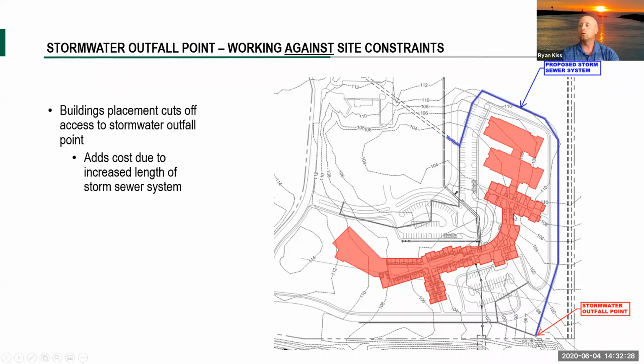it's kind of a longer, irregular shaped building, and it's doing a couple things to us. One, with the topography, that natural drainage pattern, if you recall, runs down the middle of the site and wants to come on down through these contours and hit this point. So we've created kind of a dam in our site by placing the building out here in the middle. We can fill this in. We can start to deal with that. It's doable. Again, we're raising construction costs by bringing in dirt.